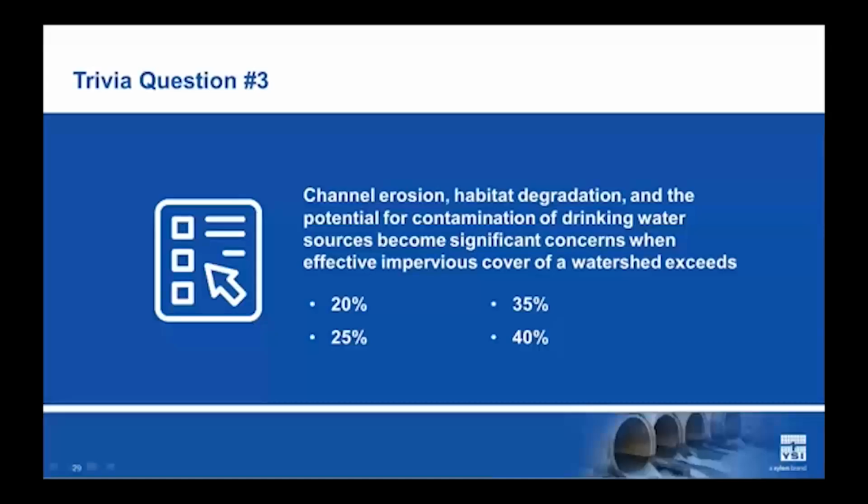Vijaya had asked how the downstream monitoring system was placed in the water, and I think, Vijaya, you were talking about how it's anchored, related to that oil refinery system. The box that we showed you is sitting beside the river, a little way up the bank, and is bolted down. Then there's a conduit that delivers the power, and the Sontek IQ is anchored to a block that is in the river. With the way it's anchored, you have to calculate its distance from the bottom to get a very good measurement of water level and flow as it changes in that river.